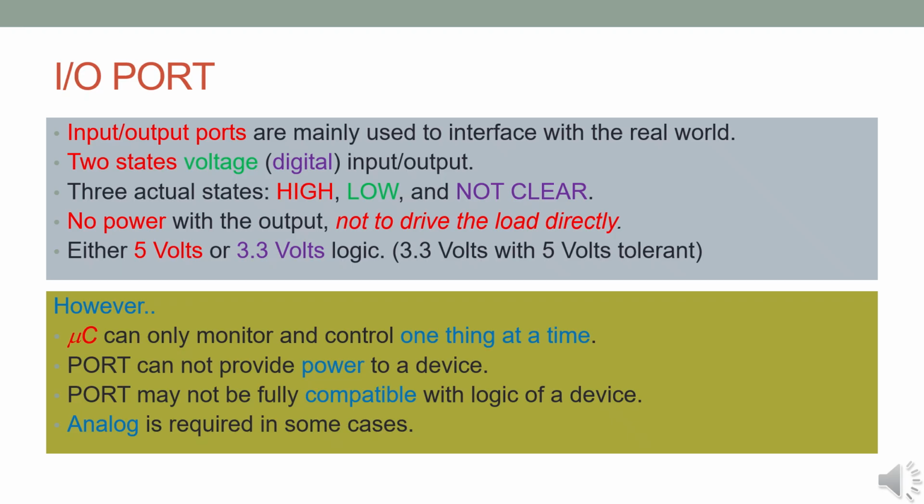Another important consideration is sequential processing. Microcomputers like the Raspberry Pi process one instruction at a time, in order. This means they can only handle one operation per cycle, which must be kept in mind when designing time-sensitive or parallel systems. To address the limitations of GPIO output current and signal reliability, developers often create interface circuits. These may involve transistors, logic-level shifters, or driver ICs to ensure that signals are safely and effectively transferred to and from external components.